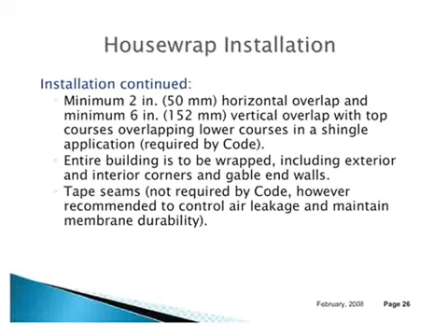The other important item is to make sure you cover all the walls. One of the areas that's commonly overlooked is the gable ends of the buildings. You want to take the house wrap material up into that area too. Now, taping the seams is not required by the code, but it's a good idea to tape the seams, both for air permeance requirements and to make sure that the membrane will be durable over a period of time.